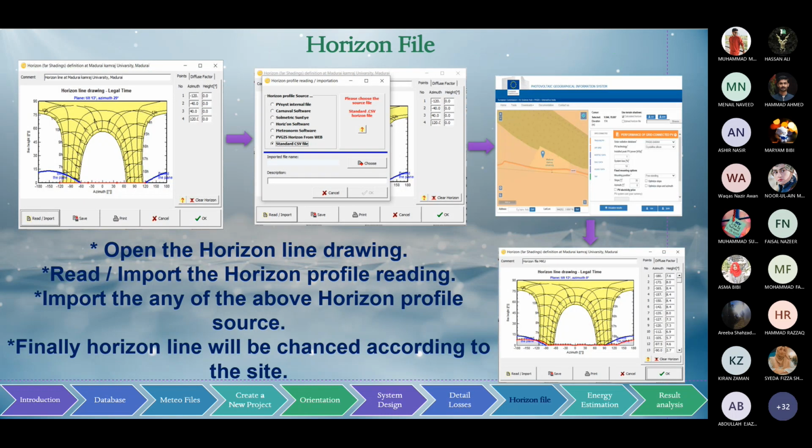So this is for Harrison 5. Once we have our location, we are proposing the solar PV module on the rooftop or ground mounted. So is there any nearby shadow throughout the year? What shadow falls on the solar PV panel, how much, and at what time? All the experts came to know this from PVsyst. This option is available; we need to use the shadow screen option.